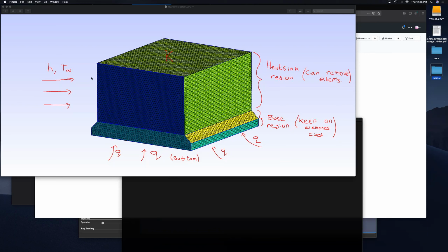Sorry, what was the question there? Well, if you're going to do topology optimization and you have this convective boundary condition where Q equals H delta T, and it's applied on the surface, but if material is removed, the surface is changing. And now that convective boundary condition needs to be applied to the new surface. So that is what you have described.